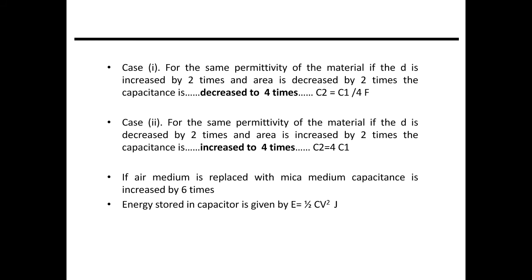If, for the same permittivity of the material, d is decreased by 2 times and the area is increased by 2 times, what will happen to the new capacitance? The new capacitance value will be increased by 4 times. It is a very important point.